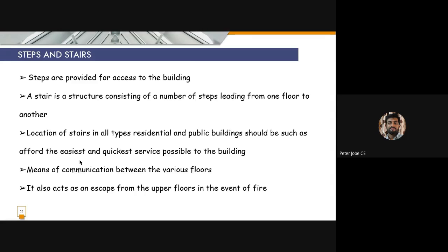So there will be people having good health. They can climb the steps very easily, while for old age people, it will be difficult to climb that easily. So the height of each step should be maintained within the limit, and in most cases, the height of each step will be kept as 15 centimeter. That's the optimum size of a step. And steps are provided for the access to the building, and a stair is a structure consisting of a number of steps leading from one floor to another.